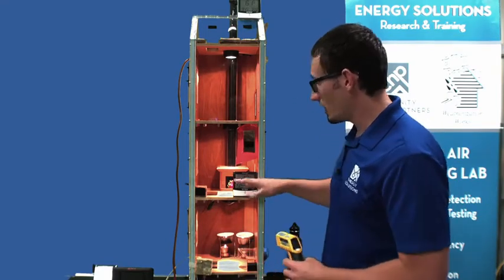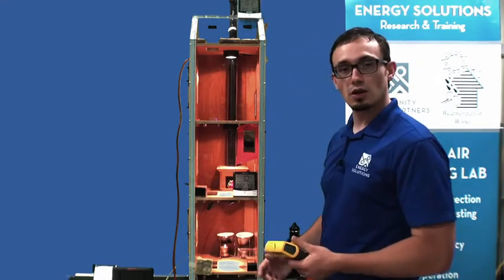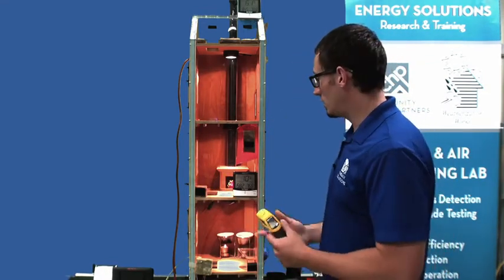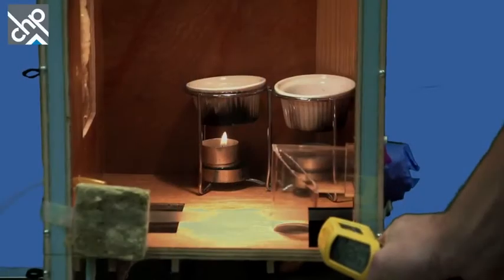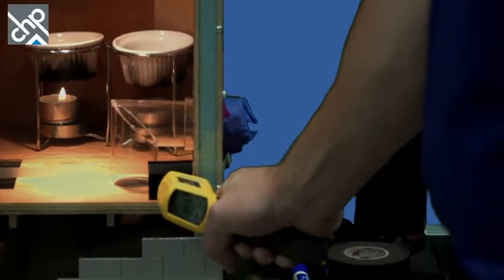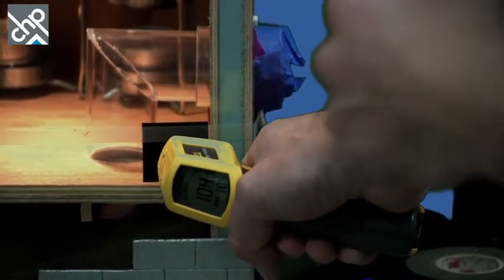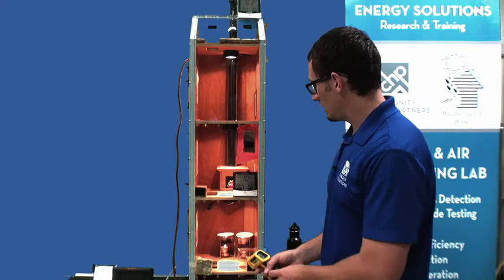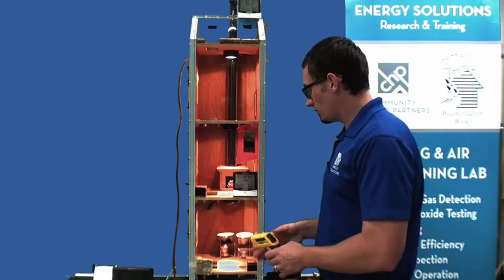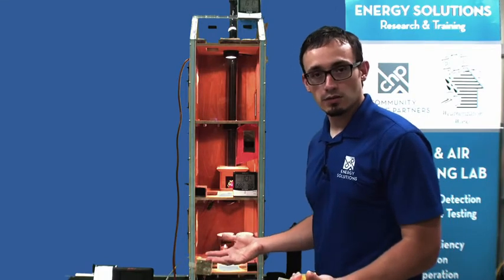So we'll set the stage here. Again, my dew point is 76.6. I don't see any condensation occurring here. I've got nothing going on. Maybe there's a reason for that. So I'm going to shoot here about an inch away. My dew point, 76.6. My surface temperature here, I'm at 102. 102 even down here. Because I'm not below dew point, I have no condensation. I've got no chance for condensation to occur.